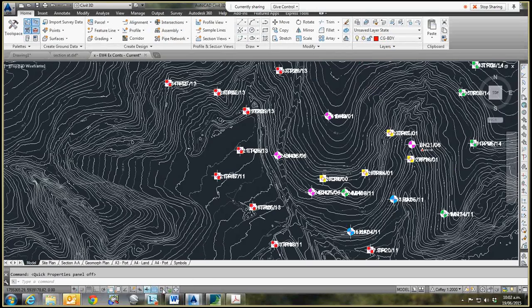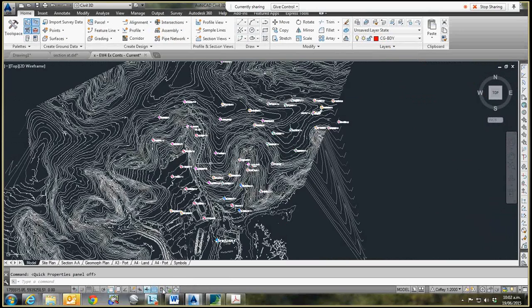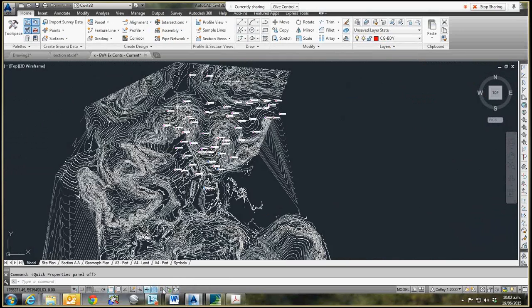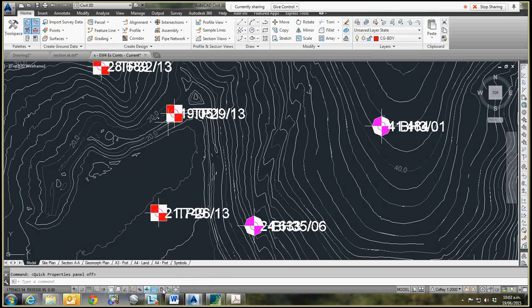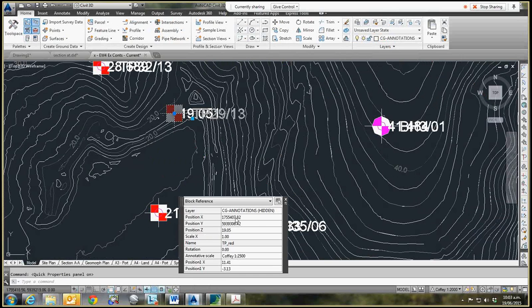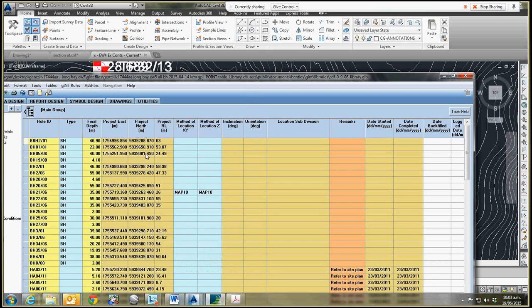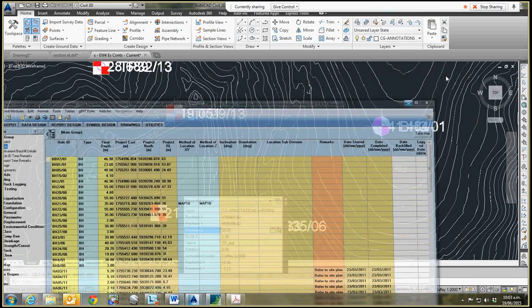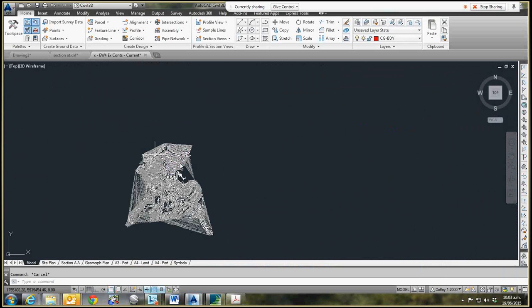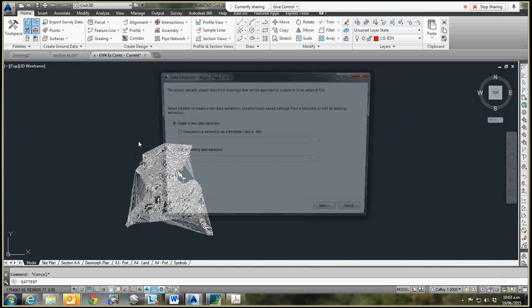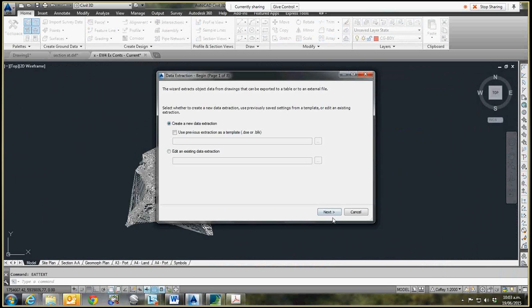The easiest way to get your elevations and things like that is you can get it individually by copy, copy, copy, and then paste, paste, paste into the appropriate fields in here. Or there's another trick called EATTEXT. It's the command EATTEXT, and it's called a data extraction.